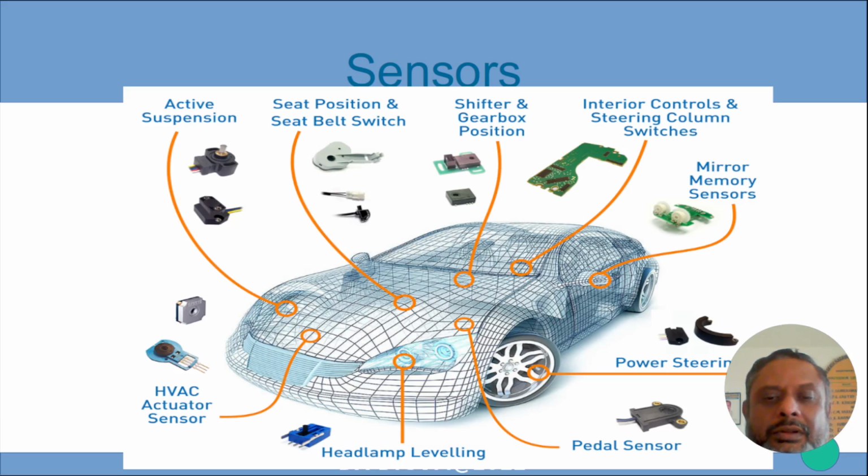But now the more intelligent cars are looking at how long the seat belt is pulled. It should be pulled sufficiently long enough so that it wraps around a person. If you don't pull it sufficiently, then it makes out that the person is not supported by the seat belt. It's just hooked behind him. Therefore, again it starts the alarm.